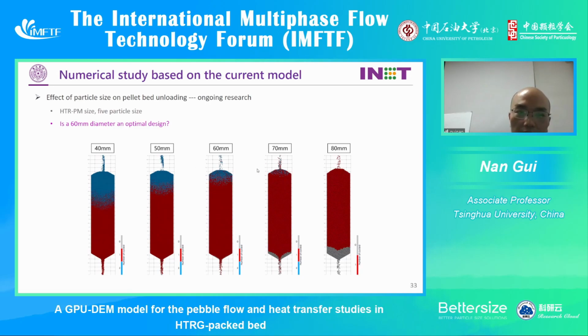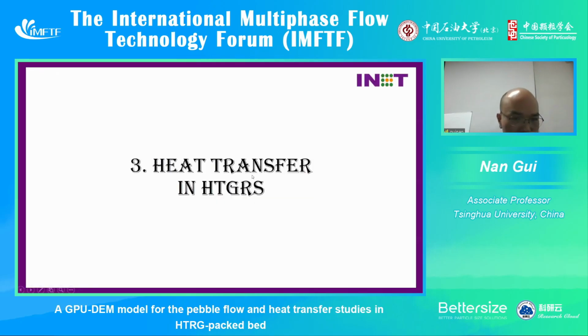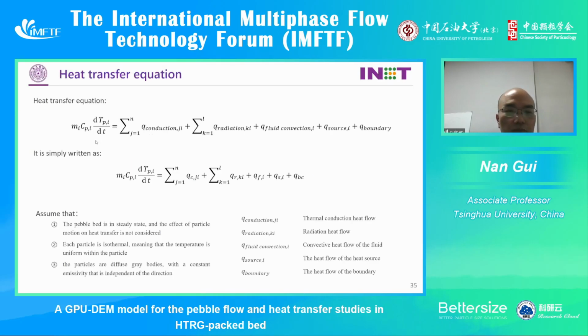So we can verify it's applicable. It can be used for real reactors. And the third part is heat transfer inside the bed. This is the governing equation for each pebble, and the heat flux for each pebble is generated by particle-particle conduction, particle-particle radiation, and particle-heating-gas convection. Also, the nuclear fission reaction inside the pebbles and from the boundaries.